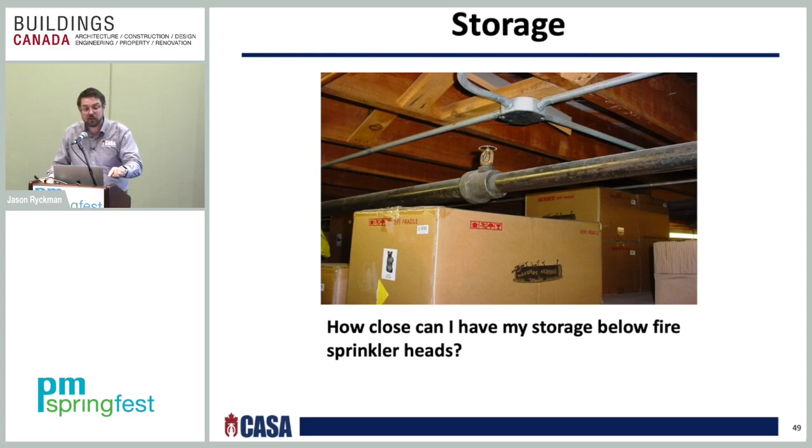Now, there are some exceptions where it has to be more than that. If you have tire storage, it has to be 36 inches. If you have special sprinklers, such as ESFRs or CMSAs, ESFR is early suppression fast response, CMSA is control mode specific application, which are storage-type sprinkler heads, you need 36 inches, not 18 inches. The reason for that is the development of the sprinkler stream.